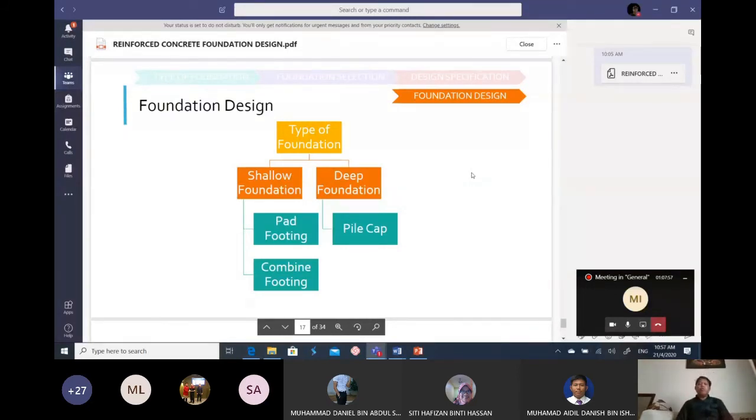If you use a pile foundation, you have to know the number of piles in the group based on the pile capacity. For example, if each pile capacity is 600 and the load is 1000, you need at least 2 piles, so a 2-pile group.